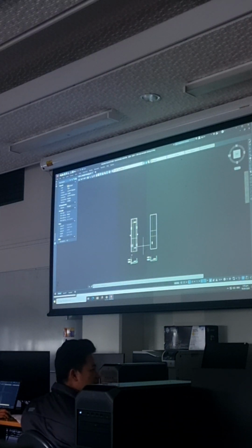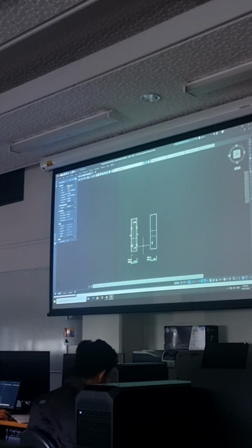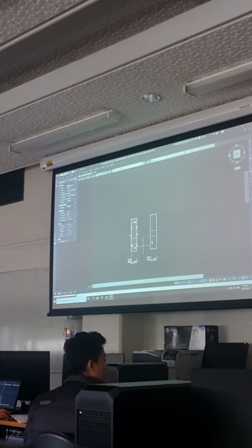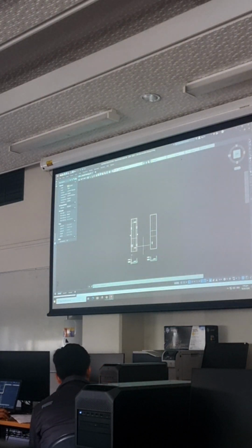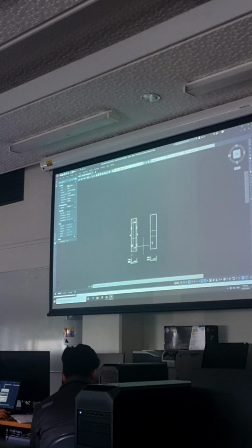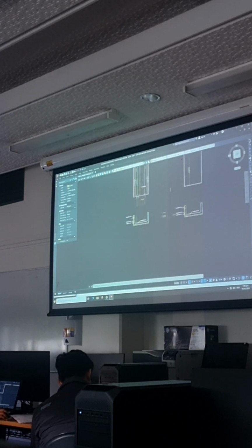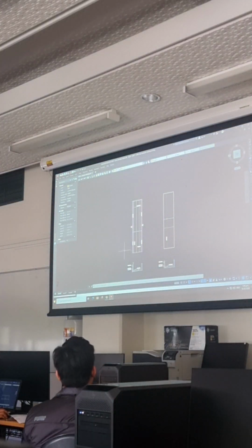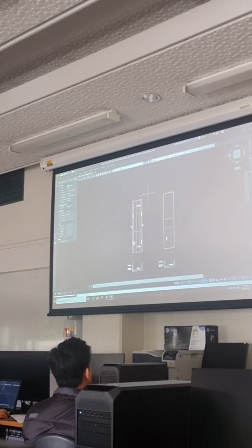And then move on to here. Now you will also have to remember a couple of other things. Do not put any dimensions on here. It's a sectional view. And do not show that view in the viewport. So when you do your viewport, make sure you only show the plan view, please.